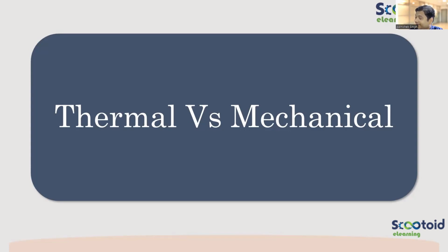Chem. Okay, that is the chemical or the process engineer. In industry, we call it process engineering. They will be responsible for giving you all the input data: the design pressure, temperature, type of heat exchanger, number of tubes, size of tubes, size of shell, everything will be given by the process.